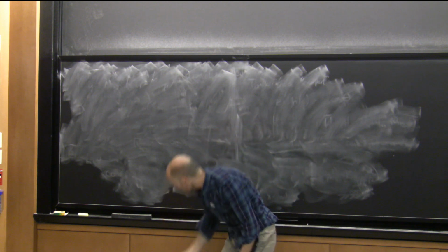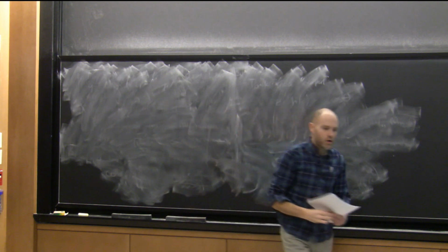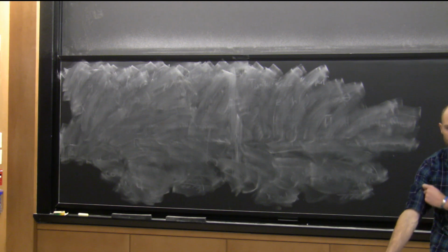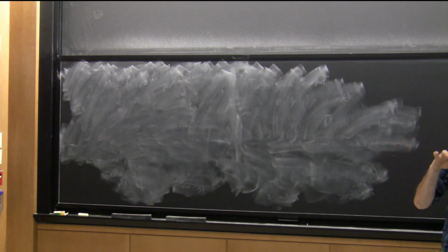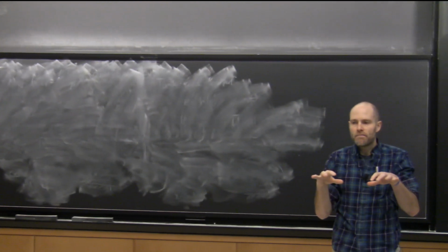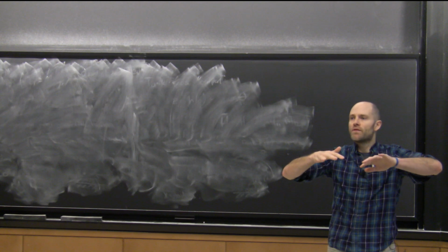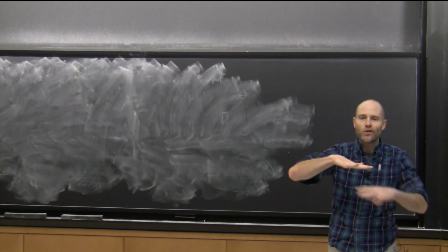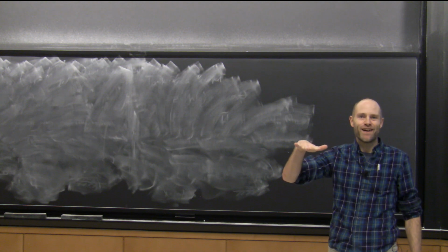For cart poles and acrobots, partial feedback linearization and energy shaping has been the story. It's sort of the big story in those fields. Quadrotors I put in the same set of lectures, and LQR works for both of them. But quadrotors are actually so easy that LQR works for a big range of initial conditions.